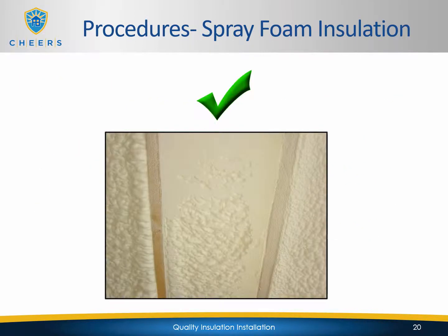And this is an example of a good installation of spray foam insulation. Obviously it's filling the whole wall cavity. There is no discoloration. So this would be a pass.